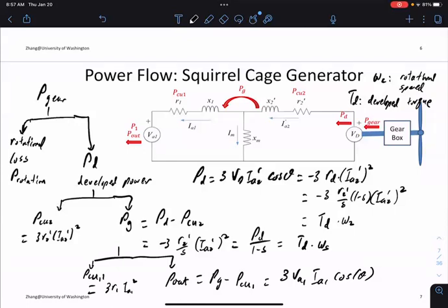But if we have a sign convention that makes generated power negative, then we actually need to add the loss at each step. So you think of generated power as a negative number. After the gearbox, you get a very negative number. So you add some resistive loss to get a smaller negative number, meaning that at the output, you have less power being generated. You can do it that way, but it's very easy to make mistakes that way because it's more intuitive to think of subtracting losses from generated power. So it'd be easier to turn the sign around and think of the generated power as being positive and subtract off the loss.